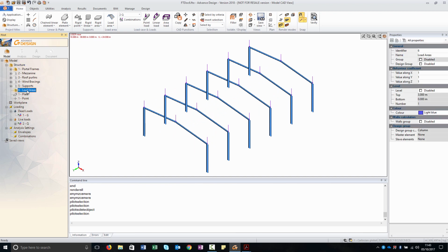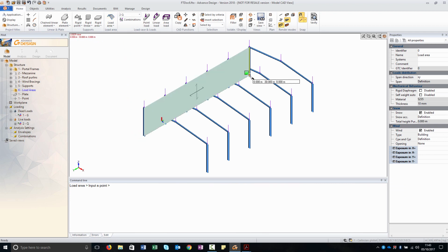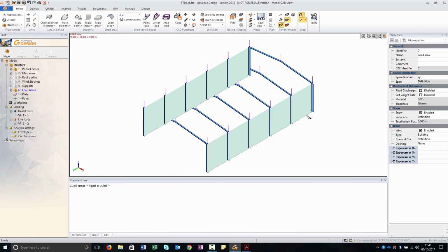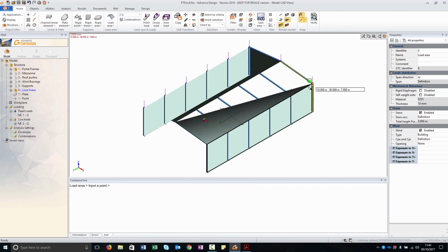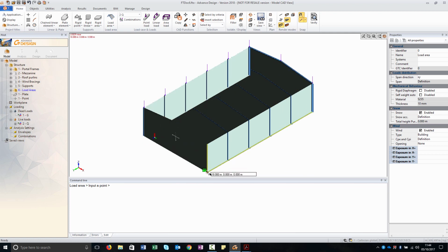Select the Load Areas subsystem from the pilot. Access the Create a Load Area Element command on the Linear in Plate toolbar. Draw the load areas on the framework lateral sides and on the roof slope. The X direction is given by the first 2 points you snap to, and the Y direction is given from the following snap point.